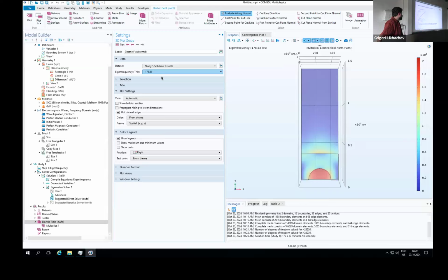Okay, I took that the average penetration depth in my mirrors was about 10 microns. And again, if you do the FDTD, now you don't just take the phase of the S11 parameter, but you take real and imaginary part and you calculate the magnitude, then you get the reflectivity. And so we see that the reflectivity of this mirror is very high, especially within 190 and like 205 terahertz. We are like 99 point something, a lot.